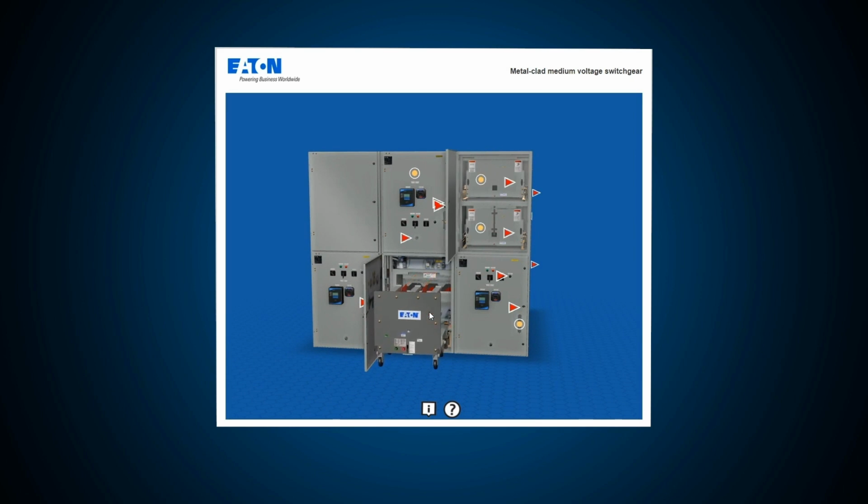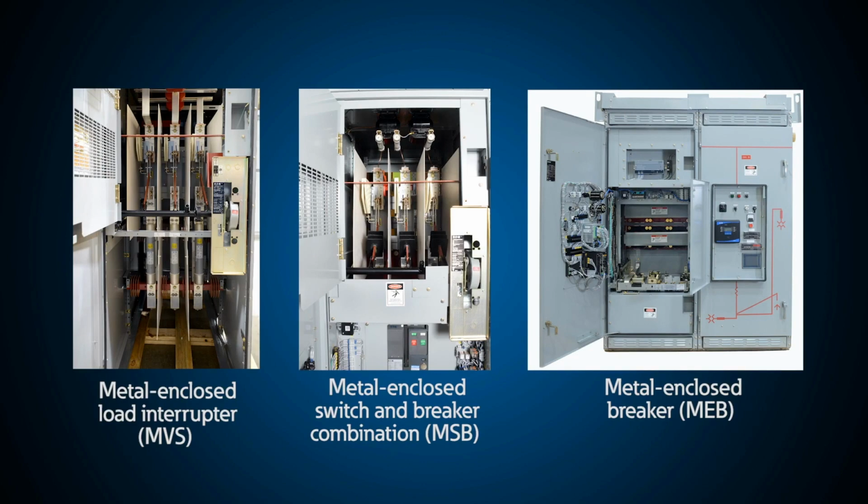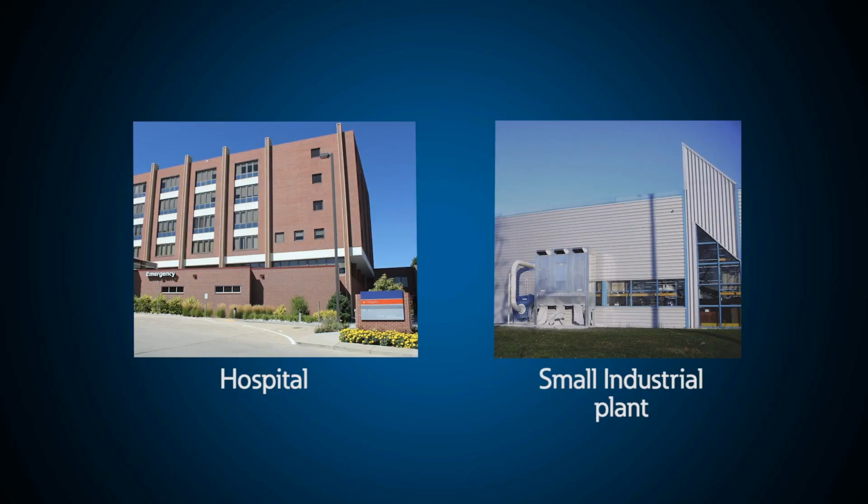Metal-clad switchgear features draw-out circuit breakers for ease of maintenance and is often applied in industrial facilities and in electrical power generation and power transmission facilities. Metal enclosed switchgear contains circuit protection devices including circuit breakers, power fuses, and fusible switches, as well as control and metering equipment. These devices can be fixed mounted in common compartments and do not require the separate barriers or compartmentalization required in metal-clad switchgear. Metal enclosed switchgear is applied in commercial and many industrial facilities where the rugged construction of metal-clad may not be required.